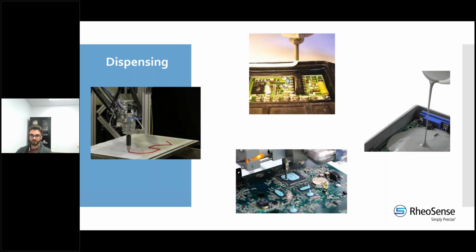So depending on the type of dispensing method, the materials and the viscosity of those materials can change quite a lot. Also, another factor for the viscosity is that the temperature of the environment you're in also affects the viscosity. So this is another factor. If you're at colder temperatures, usually your materials most likely will have a higher viscosity. If it's a little warmer, it might be easier to dispense. So a lot of these things to take into consideration.